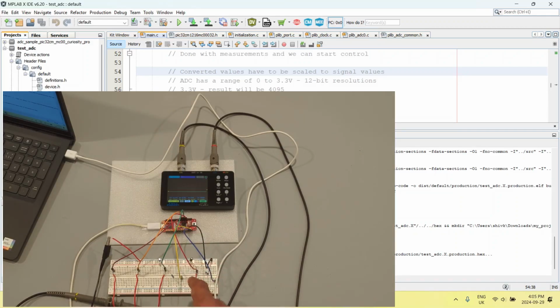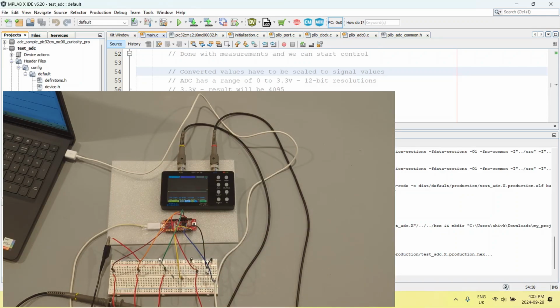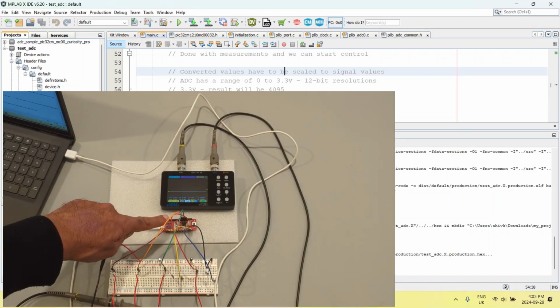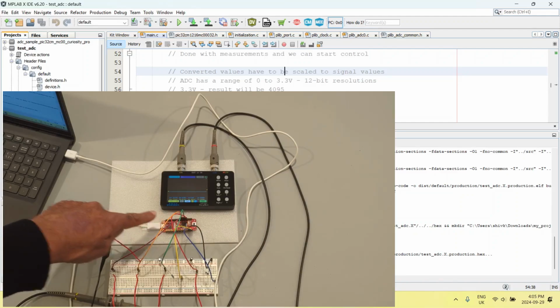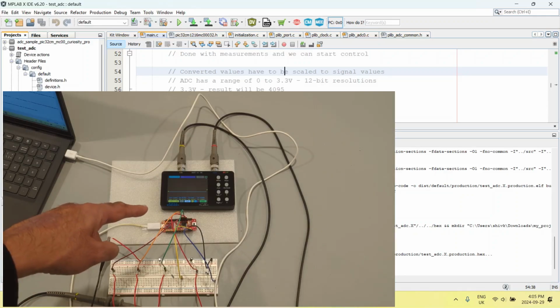Now I am taking the voltage across the capacitor, which we had seen in the previous lecture were sawtooth waveforms, and feeding it to the analog input pins, which are basically the pins PA2 and PA3, which we had configured as analog input pins number 0 and number 1. And finally, I am taking the GPIO pins, that is pin PA4 and PA5, to two separate parts on the breadboard so that I can observe the pulses where we are trying to compare our internal voltage, that is internal analog signal, and generate pulses to have a comparison.